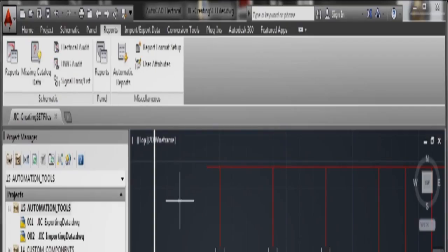We can also set up automatic reporting in AutoCAD Electrical. We can report even onto a drawing if we want to. Let's have a look at doing that now. We're going to create a thing called a set file, an SET file, which is a settings file. I've created a separate drawing for us there, creating set file, so let's add that to the project.